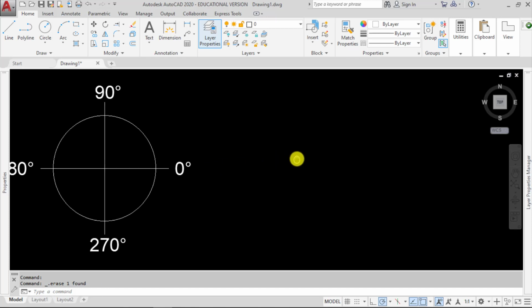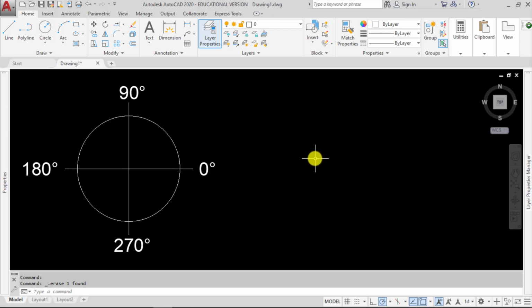Welcome back. In this tutorial we're going to cover polylines. And polylines, we touched on them a little bit in Modify Tools. Polylines are groups of lines and arcs that are joined together. So we could draw lines, arcs, etc. and use the join command to join them, or we could draw them as a polyline from the start.